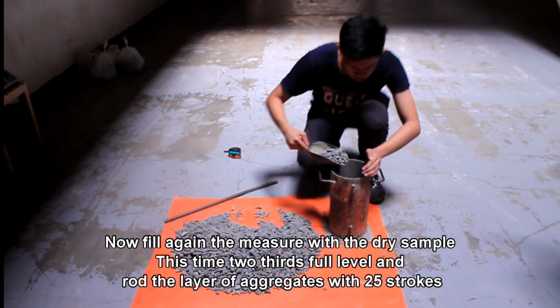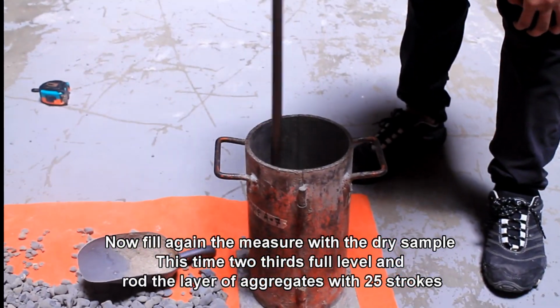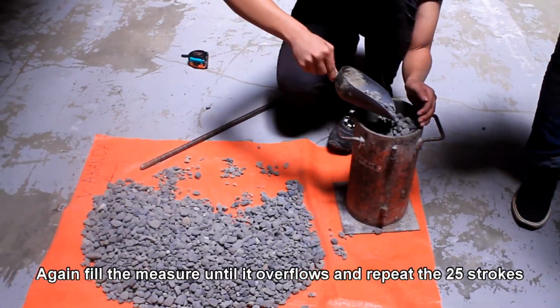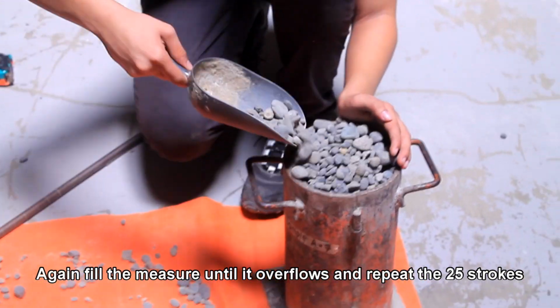Now, fill again the measure with a dry sample, this time 2/3 full level, and rod the layer of aggregate with 25 strokes. Again, fill the measure until it overflows, and repeat the 25 strokes.